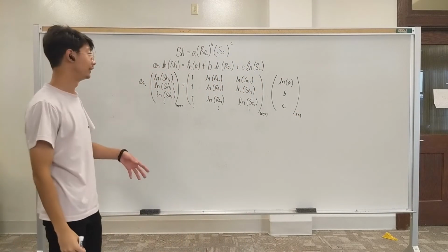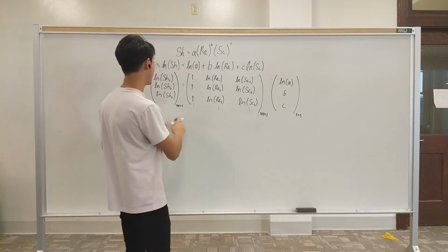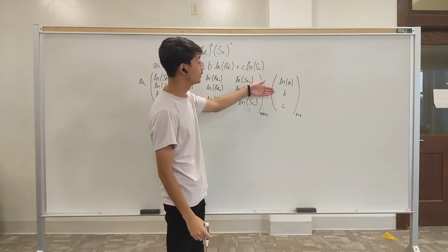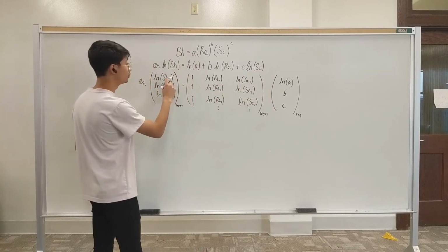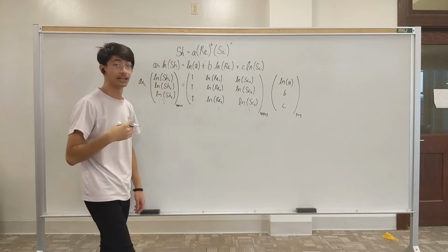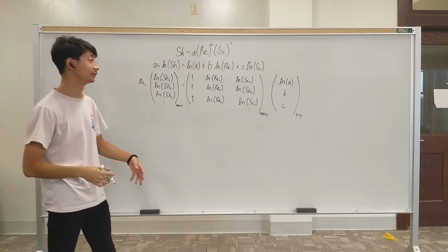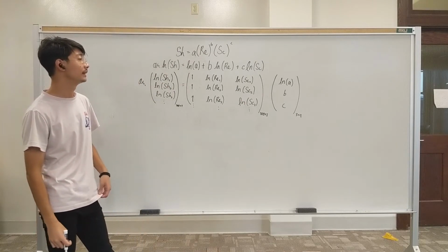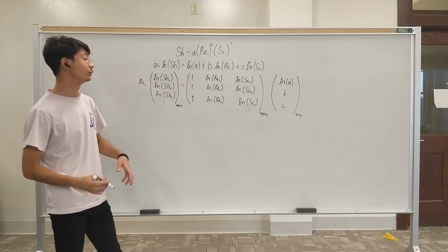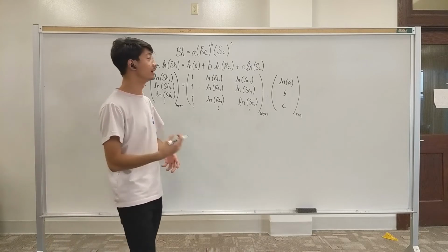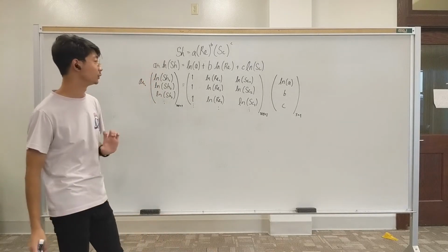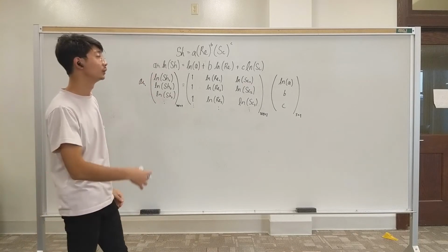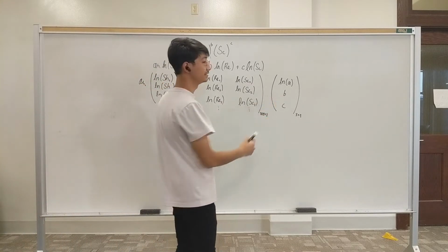Now, we have a very weird situation here where we have 100 different equations, but we only have 3 unknowns, because Sherwood number, Reynolds number, and Schmidt's number can be calculated from experimental values, whereas these constants cannot. So in normal situations, if we were calculating something theoretical, just solving 3 equations, like picking any 3 equations from the 100 equations, would give you a value for A, B, and C.